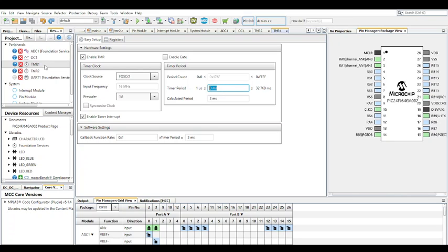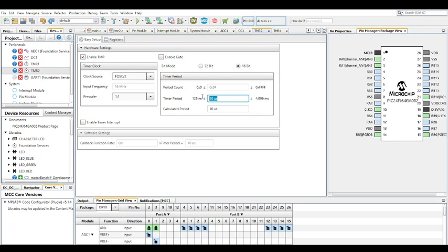So anyway, that's timer 2, that's 10 microseconds. But also another reason why we make the switching frequency reasonably high, like 100 kilohertz, is because the component sizes can be a lot less. And if your capacitor size is a lot less, it means you can get to your settling time much faster.